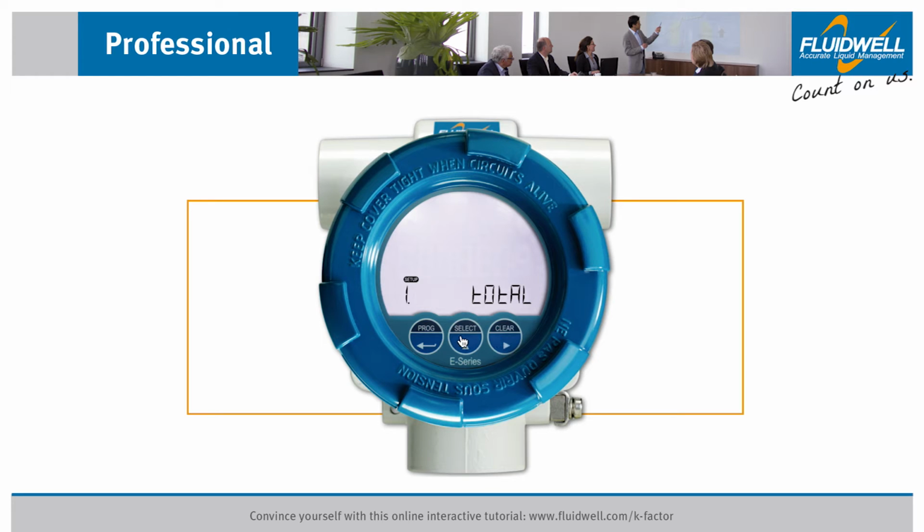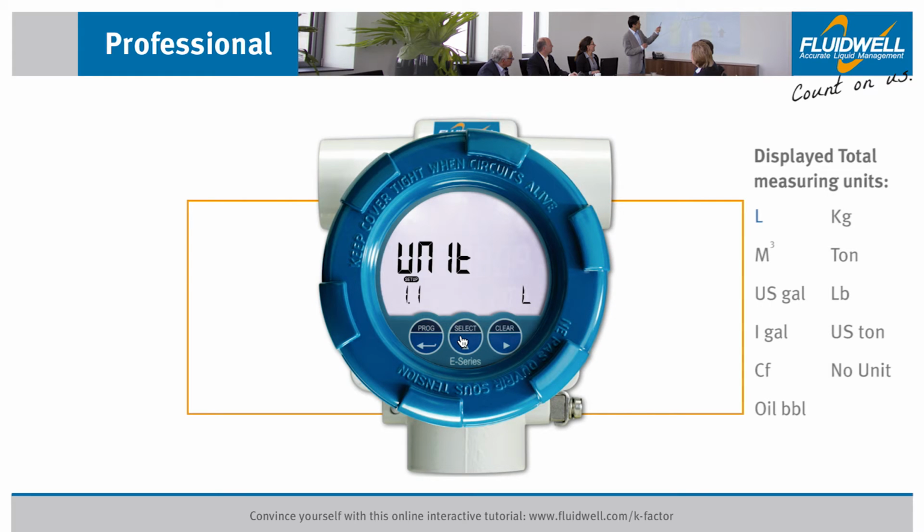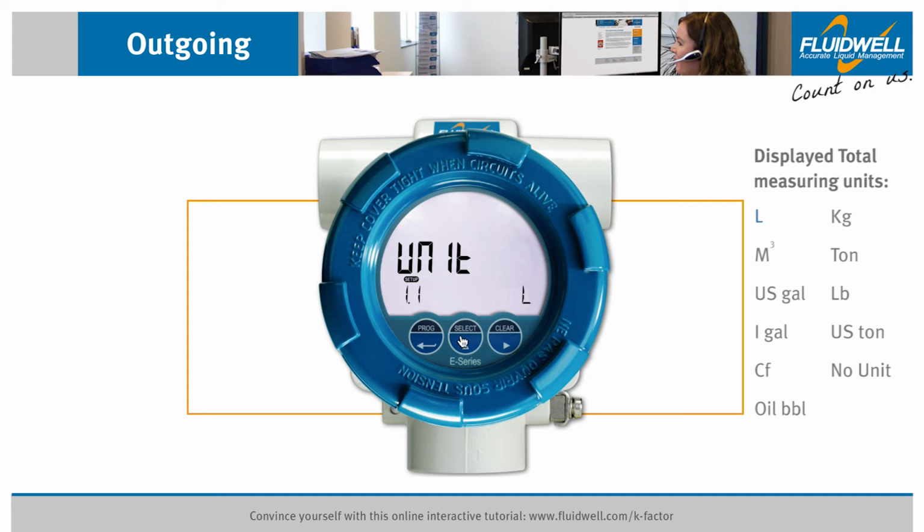Press Select to go to Menu 1.1 Unit. Press Prog to change this setting. In this tutorial, we are going to set the displayed total to kilograms. Press Prog to store this setting. A change of the measuring unit also requires a new calculation of the K-factor for the total. The calculation is not done automatically. The next step is to set the total decimal point position.